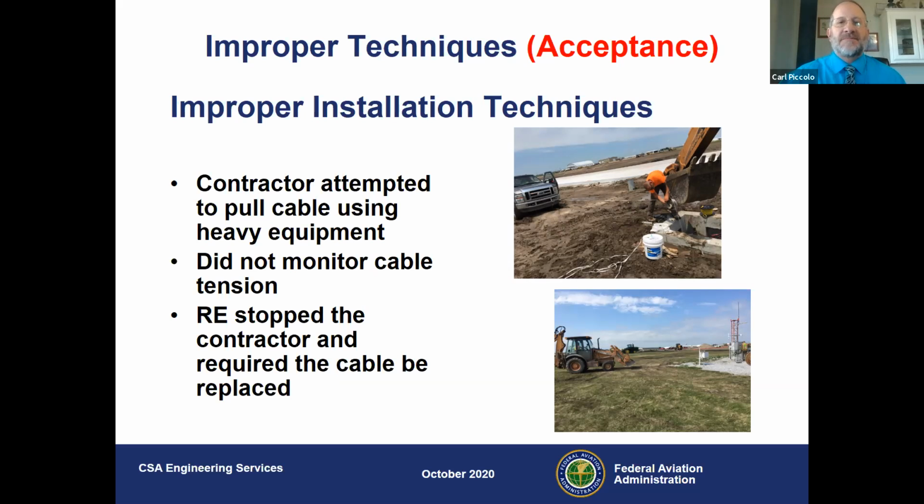And the second picture is he didn't have enough oomph in his pickup to pull the cable, so he used the backhoe the next day. So we stopped him, had them pull all that cable back out and re-pull it properly using the proper strain meters to make sure that the cable wasn't damaged during installation.